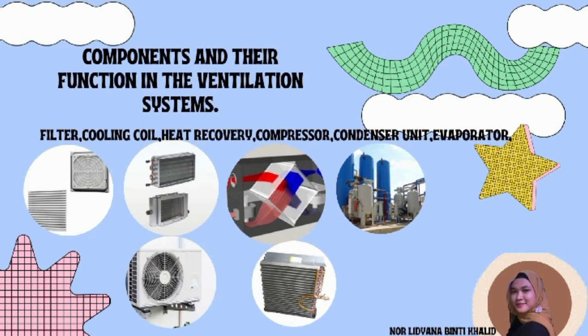The fourth one is the compressor. To circulate the refrigerant in that system under pressure, this concentrates the heat it contains. The fifth one is the condenser unit. The condenser coil drags away heat from the refrigerant and releases it to the outside environment. The last one, the sixth, is the evaporator, to cool the refrigerant so that it can absorb the heat.